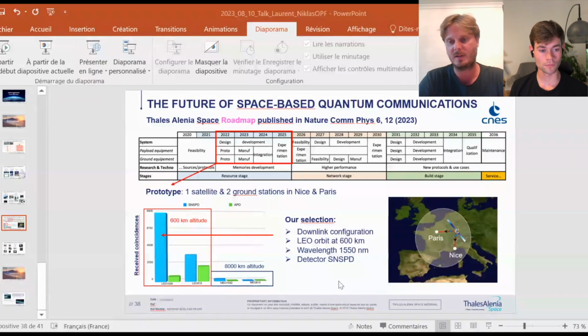and then you have radiations, and you have mechanical and thermal effects, because for a low Earth orbit, the satellite is either in the night because of the Earth, or exposed to the sun. And so you have a thermal gradient to take into account. So that's complicated to put something on board a satellite. So typically, all the devices that are critical, we try to put them on the ground.